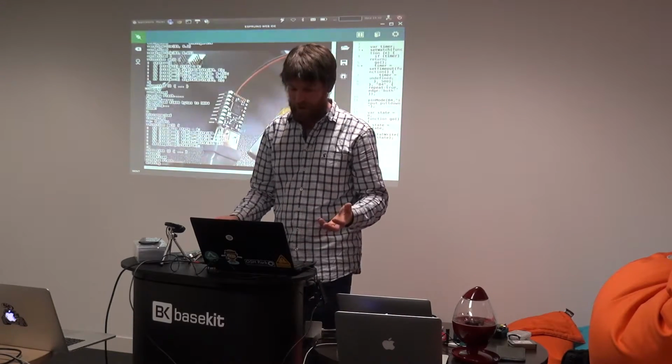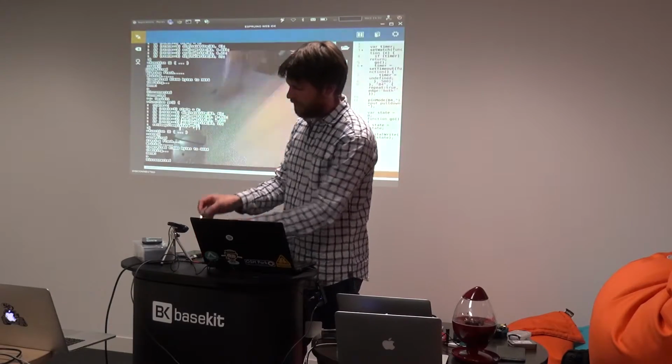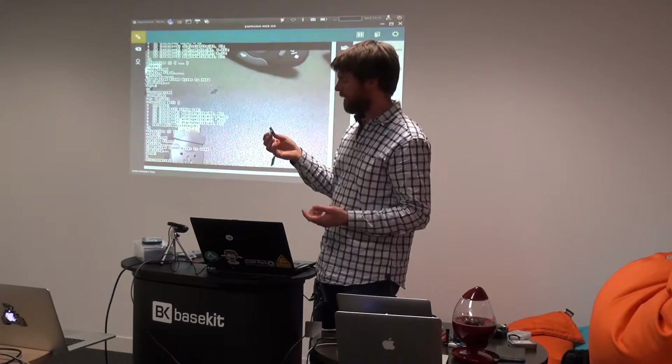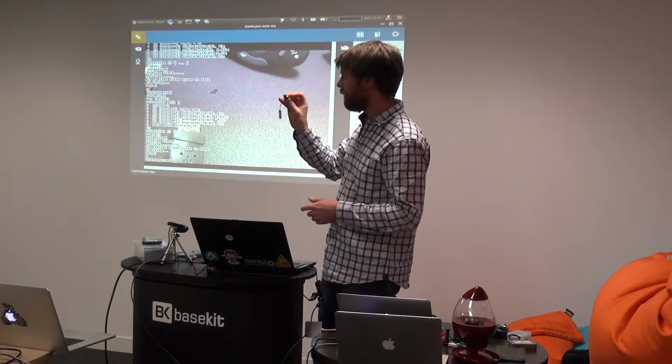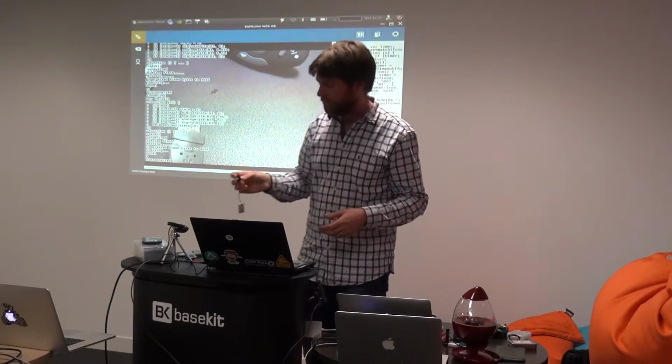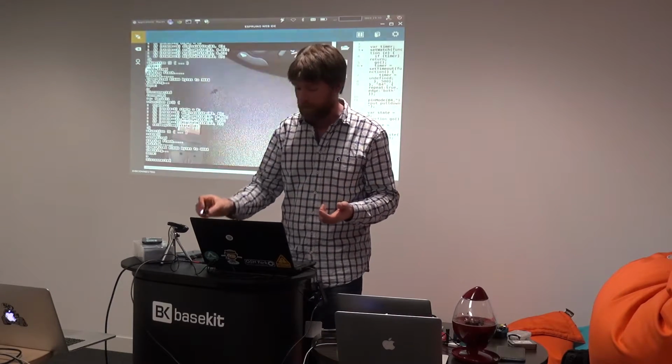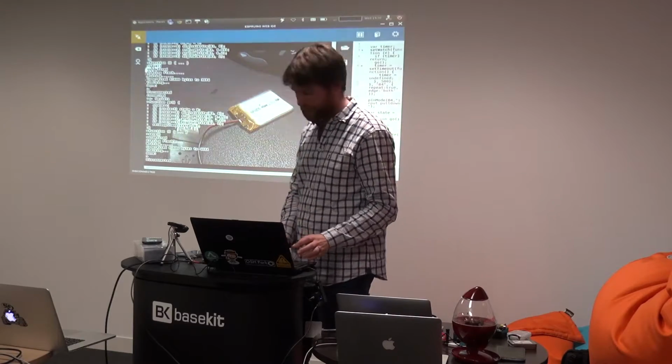Saved again. And now this chip will be drawing, when the light's off, about 0.03 milliamps. So this tiny little battery will last for absolutely months. And this is something that you could just pack up or fit with a non-rechargeable battery if you wanted, because it's really not going to be a problem.